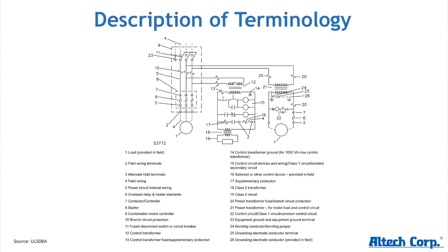You can go back to the requirements for components, 49 pages in the back of the standard. Pick out your component and then figure out, okay, what is my category control number, and search for my component. Then you are certain that nobody will flag that component, because you did your due diligence to pick the right component for the right position in the panel.